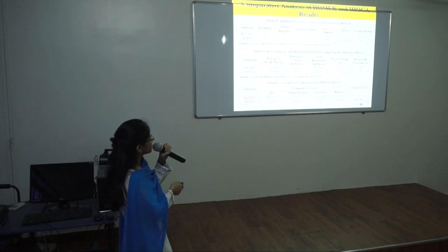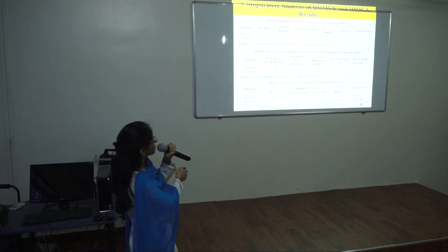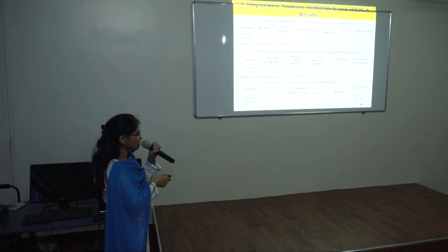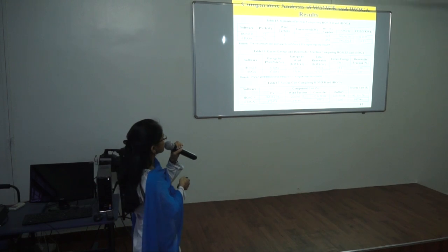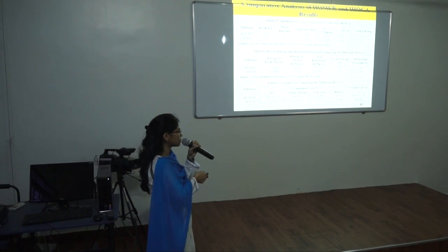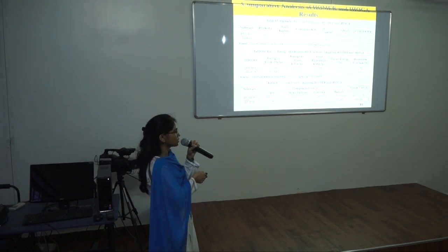On the other hand, the energy generated by the IHOGA system is higher as compared to Homer, 507,035 kilowatt hours per year, due to the large size of PV panels suggested in table 15. Looking into the values, excess energy is one of the constraints for the optimization. IHOGA will produce excess energy of 33.91% with a renewable fraction of 100%. On the basis of this comparison using table number 16, it indicates that IHOGA will generate excess energy 5.81% higher than Homer.